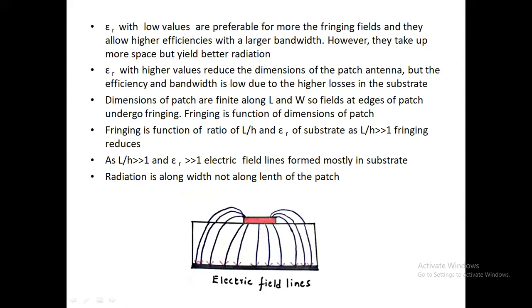So here you can observe this is the electric field formation. This is the center of the patch. I have just taken the front view of this, and the field distribution will be like this. See here, one thing we can understand. The fields here can be divided into two things, like transverse field as well as electric field. Whatever the electric field formed here gets cancelled, and whatever the field that is formed in transverse directions gets added.